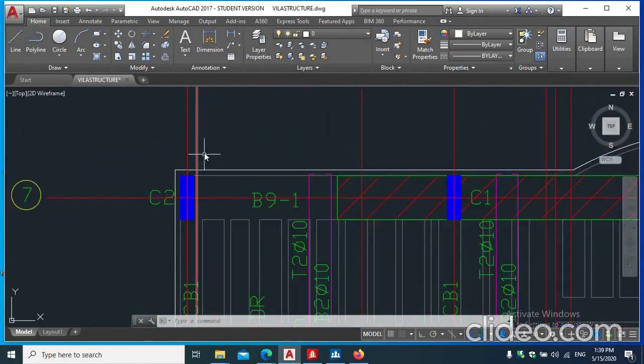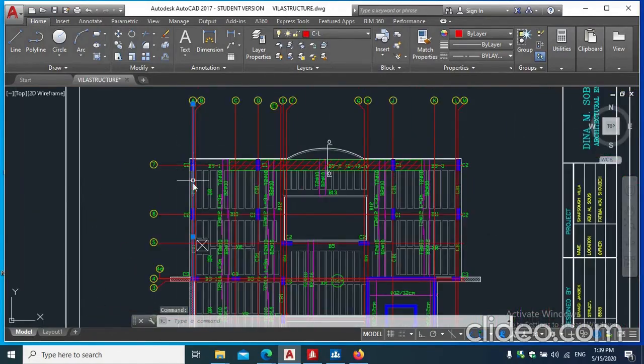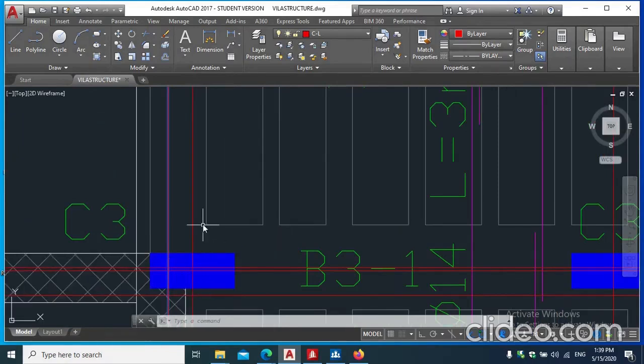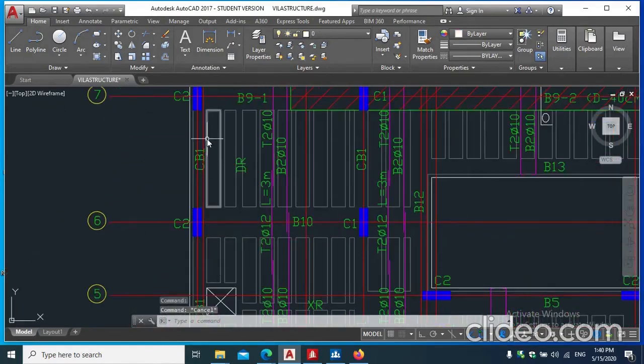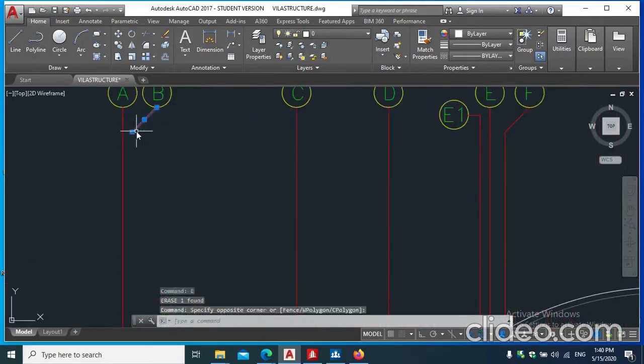You begin by trimming the grid, like this first grid, for example, passing through the center line of this column, and that column, and so on. But when you reach this column, no, its center is for the next grid. So, this grid here is made for this column. Now, instead, if you align them all on the same line, and then come to this column and do this offset, which is the distance you take from Autocad, there's no need to make a large set of grid lines. This way, you keep the drawing as centered as possible, and you might start by removing this line, for example, to make the import from Autocad as simple as possible.